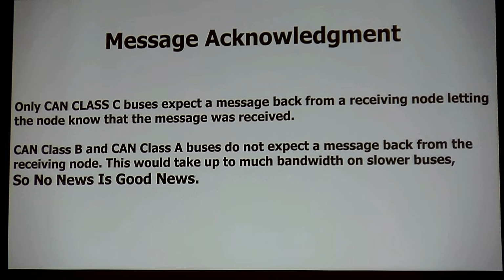It meant that it was successful in moving the data. It didn't say it was successful in talking to the dash. That's what you interpreted it as. So now you think because you programmed it and it was successful, you could talk to the module. Dude, the module's dead. He's not even alive. And you're sure he's alive because the factory said they could talk to him and he was successful. Start to understand what I'm telling you. You've got to understand some of the really weird stuff in this CAN bus, or you're going to really have some bad days.